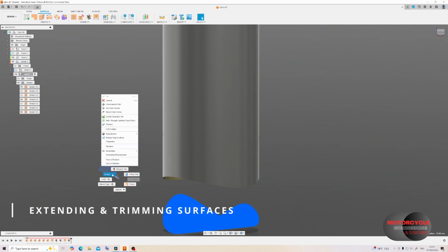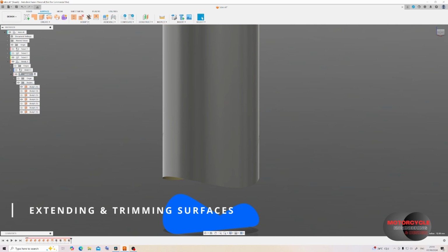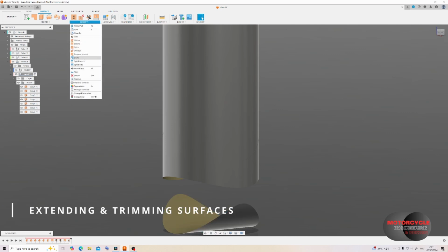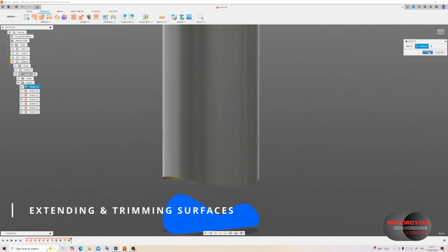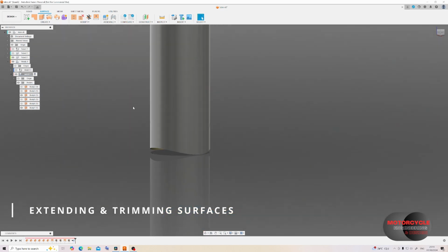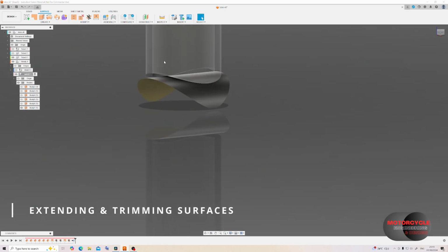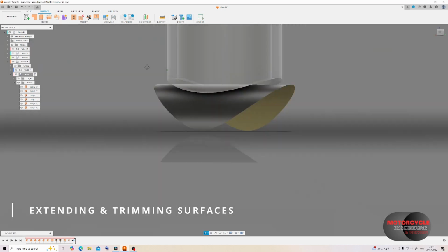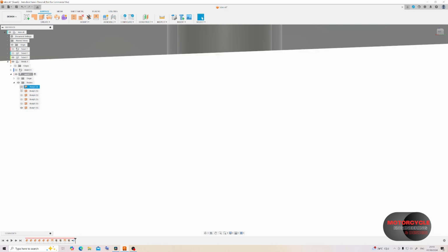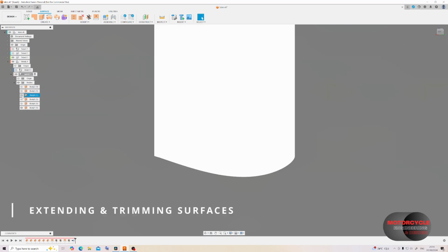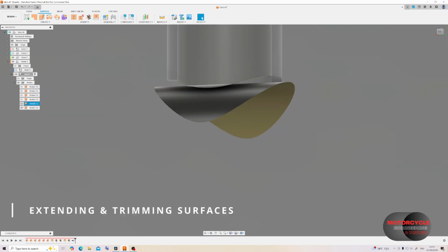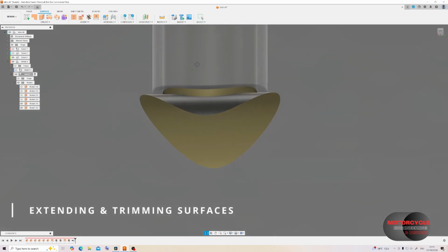We can select them and just click delete, or we can actually use the remove feature. Now I need to get the high point of the weld, so that's going to require an offset of the horizontal tube to intersect with the external surface of the vertical tube.